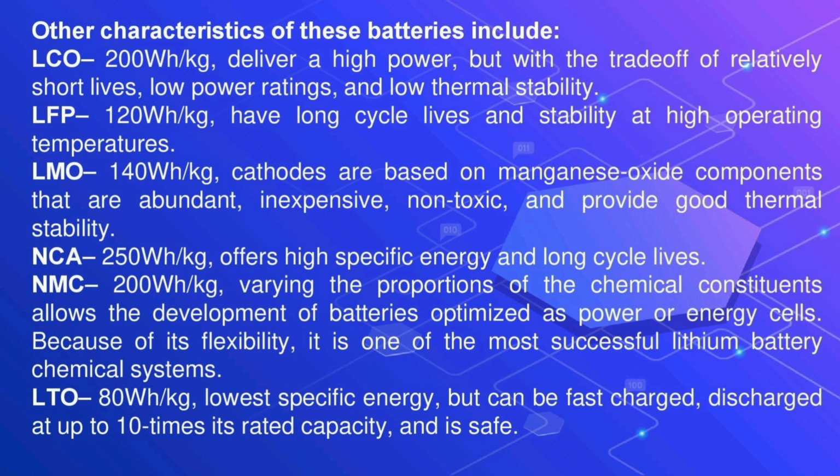Coming to charging an electric vehicle's battery, most electric vehicle charging is done at home, either through a conventional 120 volt circuit known as level 1 charging, or a dedicated 240 volt line called level 2 charging. Depending on the vehicle's battery capacity, it can take anywhere from 8 hours to more than 16 hours to achieve a full charge using level 1 charging. Though it will cost a few hundred dollars to have an electrician install 240 volt service in your garage, it will pay off in terms of charging times as short as 4 hours.